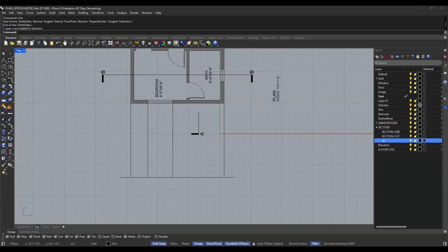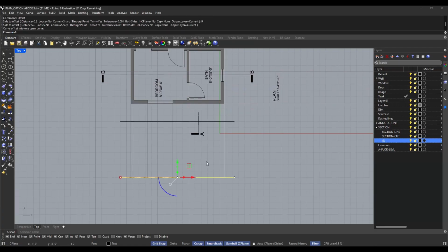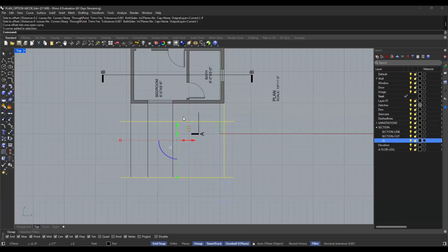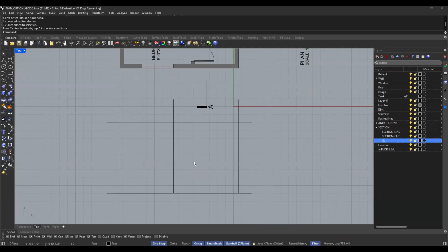So we're done with that part, and then we go with the height. In elevation, we use the total building height, not interior clear height. So the total and overall height would be 9 feet in this project. I'm going to offset the line, and then type 9 feet and hit enter. So select all those and bring this down. So overall wall height is 9 feet.